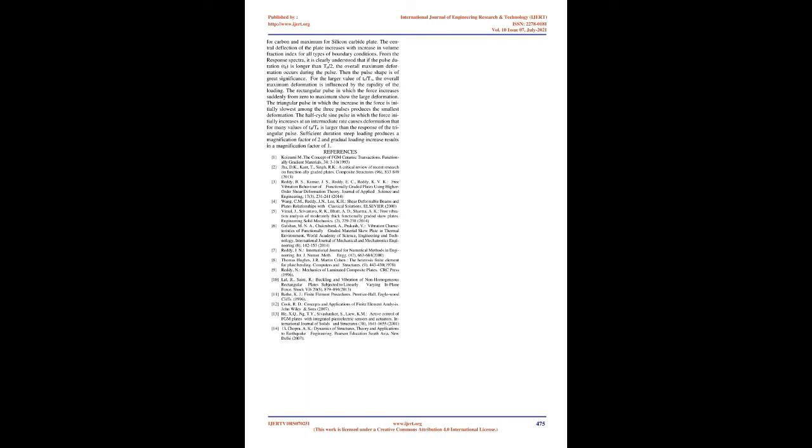From the response spectra, it is clearly understood that if the pulse duration, Td, is longer than Tn/2, the overall maximum deformation occurs during the pulse. Then the pulse shape is of great significance. For the larger value of Td/Tn, the overall maximum deformation is influenced by the rapidity of the loading. The rectangular pulse, in which the force increases suddenly from 0 to maximum, shows the large deformation.